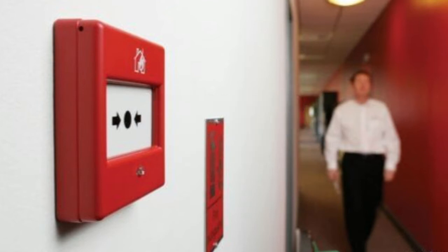They should be conspicuous, i.e. red, fitted at a height of about 1.4 metres or less for premises with a significant number of wheelchair users and not in an area likely to be obstructed.